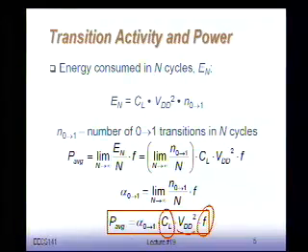And all the other ones are 0. So the probability to go from 0 to 1 is quite small if you look at a random input pattern. So you see that those gates won't switch very often. Okay? And as a result of that, switching activity is, in most chips, actually quite small. Not all those capacitors are going back and forth all the time.